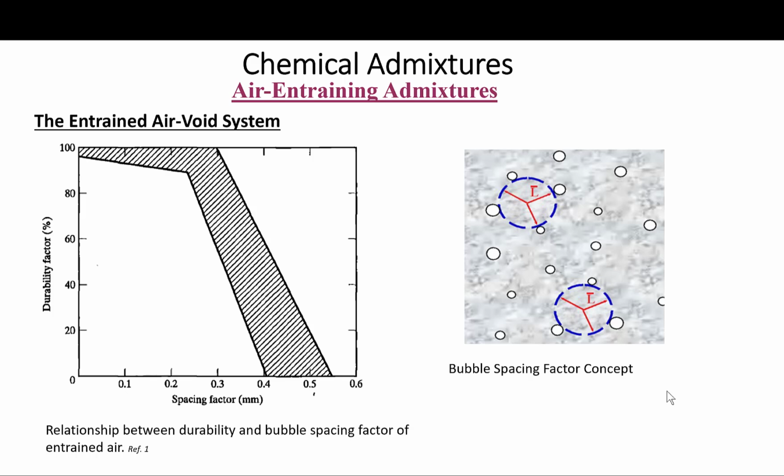Some concretes, for example those containing superplasticizers, may show good frost resistance even when the air void parameter limits are exceeded. Also, alternative parameters that give an estimate of the fraction of paste protected have been proposed to account for the random distribution of air bubbles in the paste, but I'm not sure if any have been adopted by ASTM standards yet.